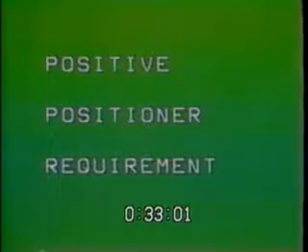Valve size is another one to consider. Is a positive positioner required on our valves? And will the valve that I choose have the linkage for a positive positioner? All of those must be taken into account before you can select the proper valve.